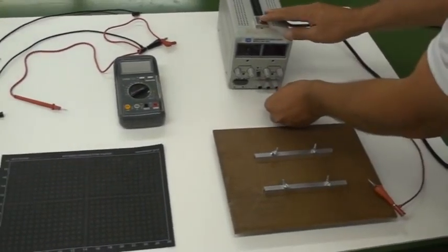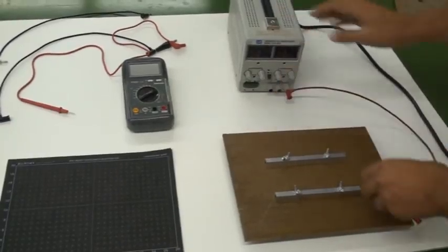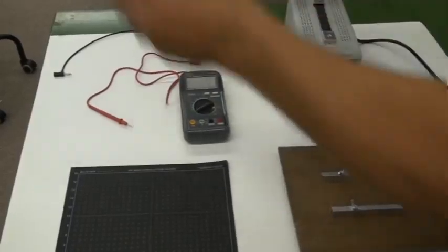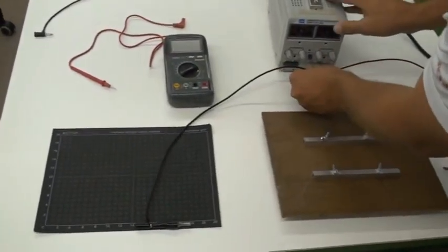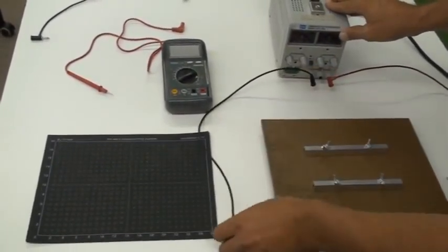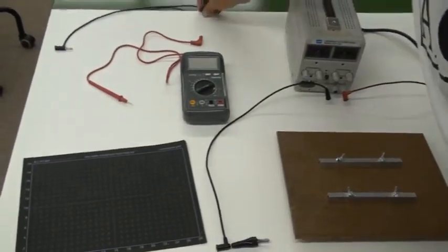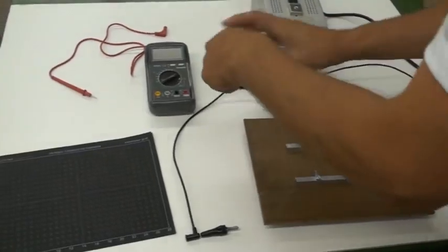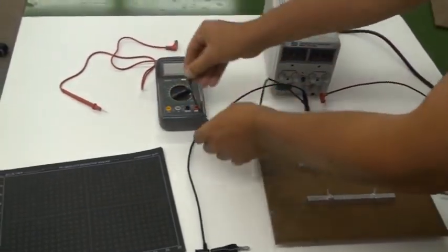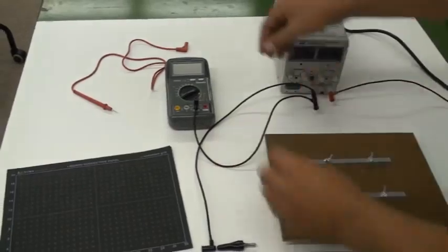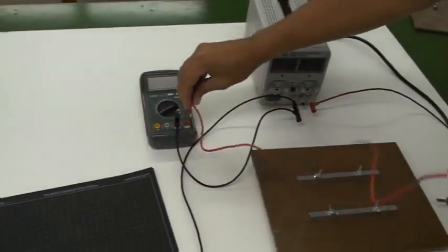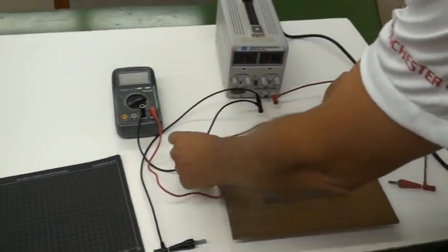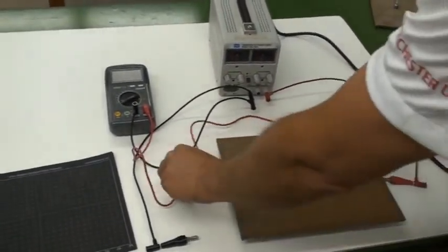The equipment for this experiment includes a voltage source, seen in the upper right-hand corner, and set for 10 volts. A voltmeter, upper left, with the common hole connected to the 0 volt side of the voltage source. The red input to the voltmeter is equipped with a relatively sharp-ended probe for sampling the voltage at any point. The dial on the voltmeter should be at the 20 volt maximum setting.